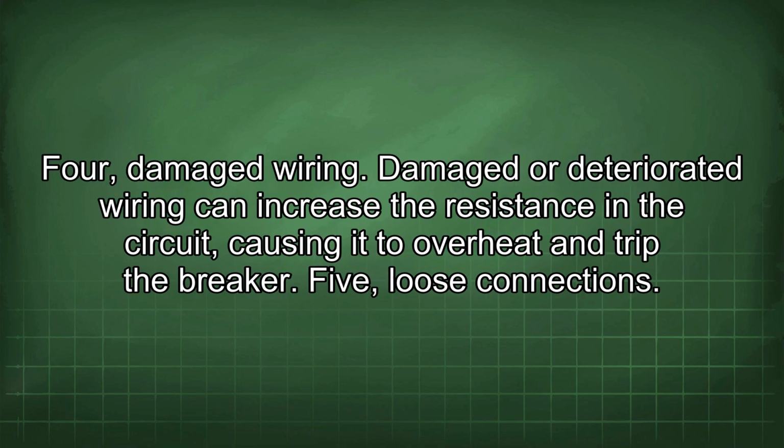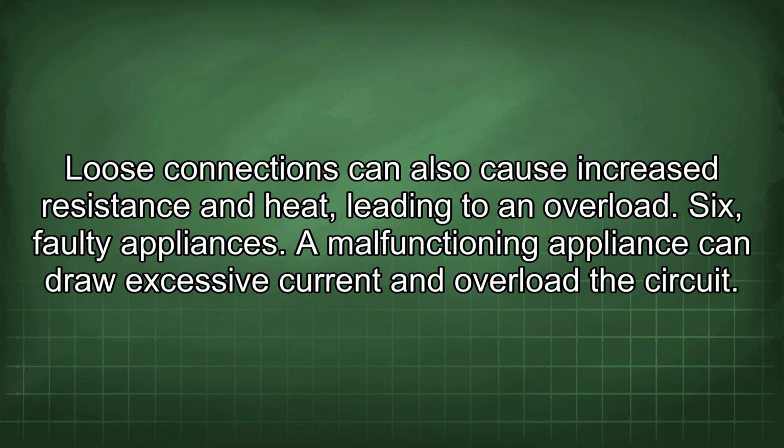4. Damaged wiring. Damaged or deteriorated wiring can increase the resistance in the circuit, causing it to overheat and trip the breaker. 5. Loose connections. Loose connections can also cause increased resistance and heat, leading to an overload. 6. Faulty appliances. A malfunctioning appliance can draw excessive current and overload the circuit.